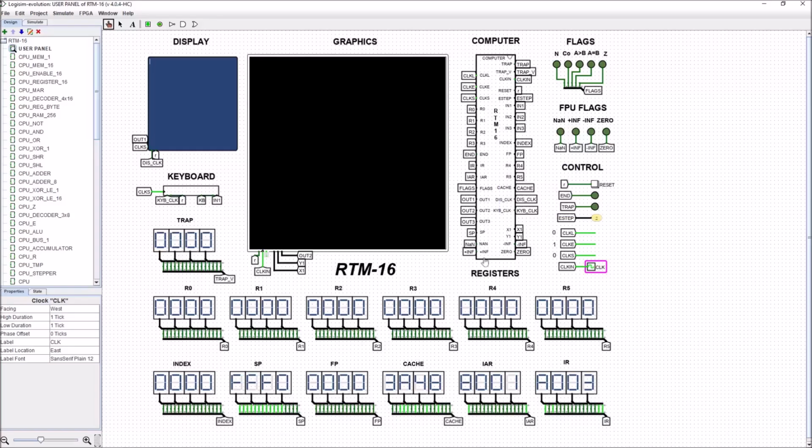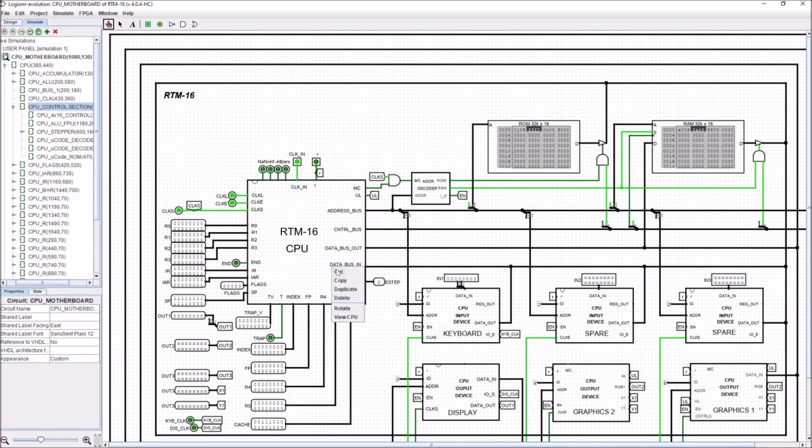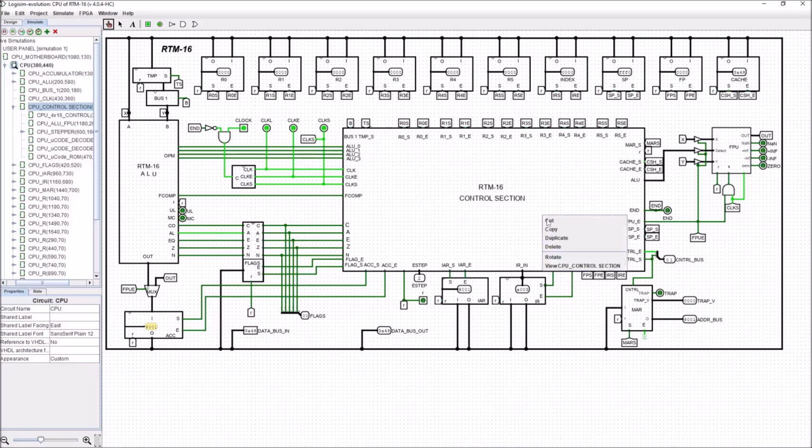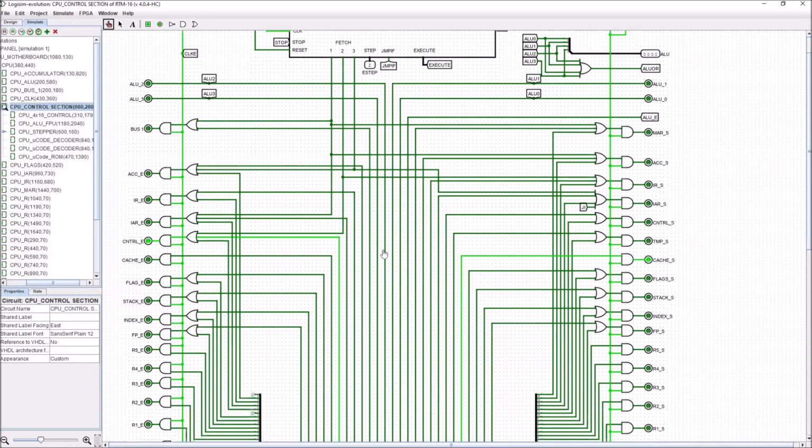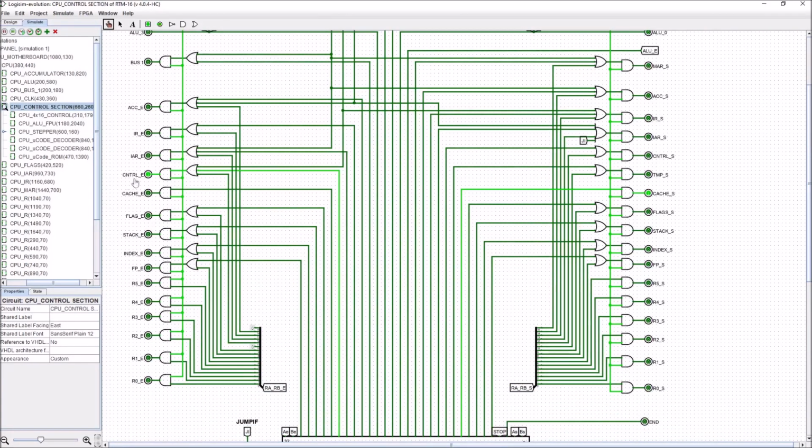And you can see in the second instruction we take the value from memory, which is our 3A48, which is the 45 degrees, and we put it in the cache register, and that's exactly what we have done here. And again, it's been facilitated simply by making the enable line here for the control enable go high, and also the cache set has gone high here as well.